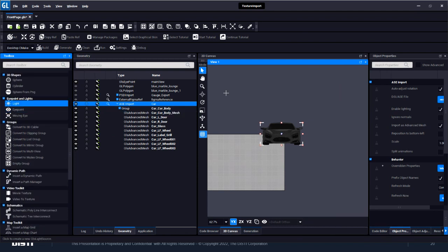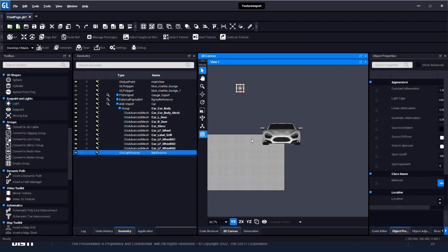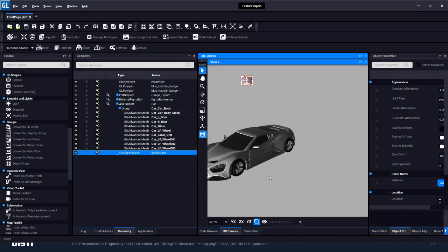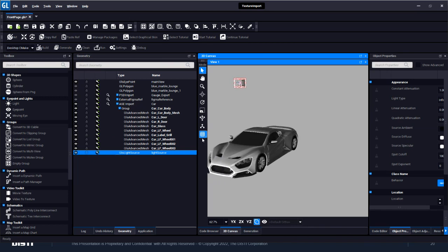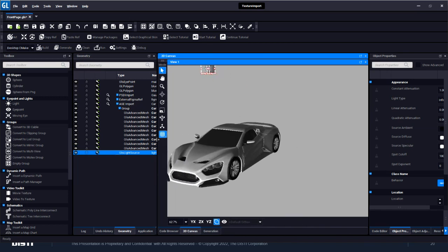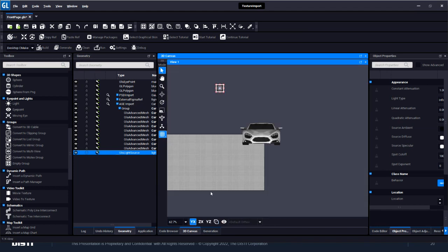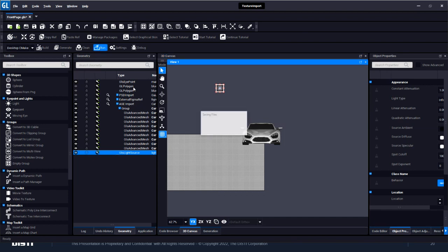So we'll just grab a light object, put that in the scene, and now it's actually going to start applying lighting to the vehicle. So we can view this in a 3D viewer here in the editor and see that the front of the car is now lit. This is kind of an infinite sunlight from the front, whereas the back still has shadow cast on it. So we'll go ahead and, same as the others, give this a run. Make sure we can see this at runtime.